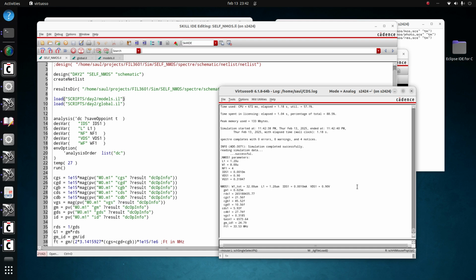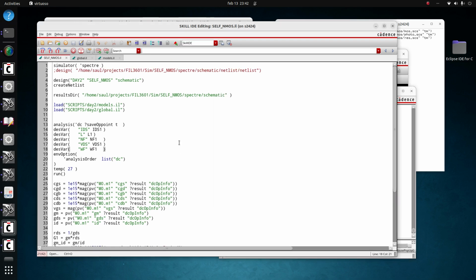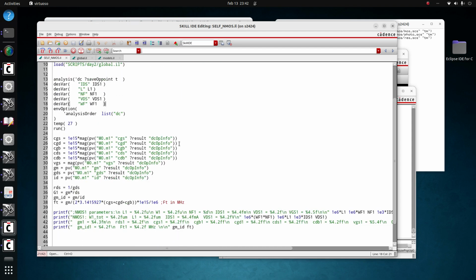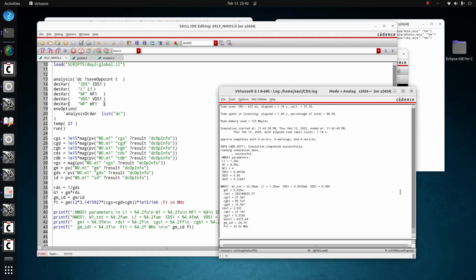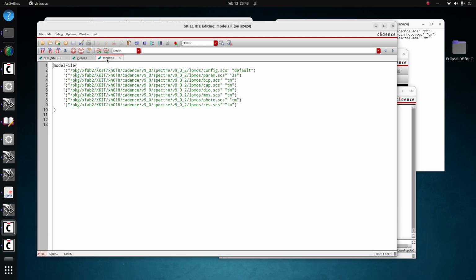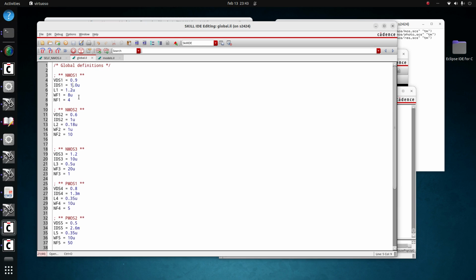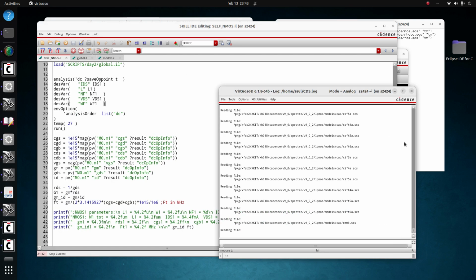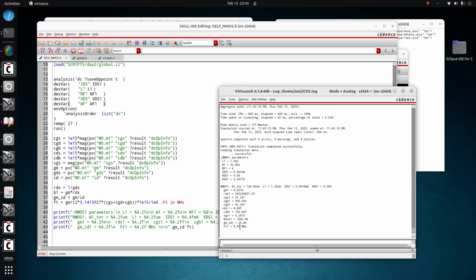So I hope you get the idea now that scripting has very interesting opportunities. Changing the schematic, running the simulation, and getting this piece of information is possible using the graphic user interface, but there is no way you can do it faster than just changing this like this, saving, coming back and running it. That is much faster, and just to get this information very quickly. Sometimes you need it very quickly, and then that is the way.